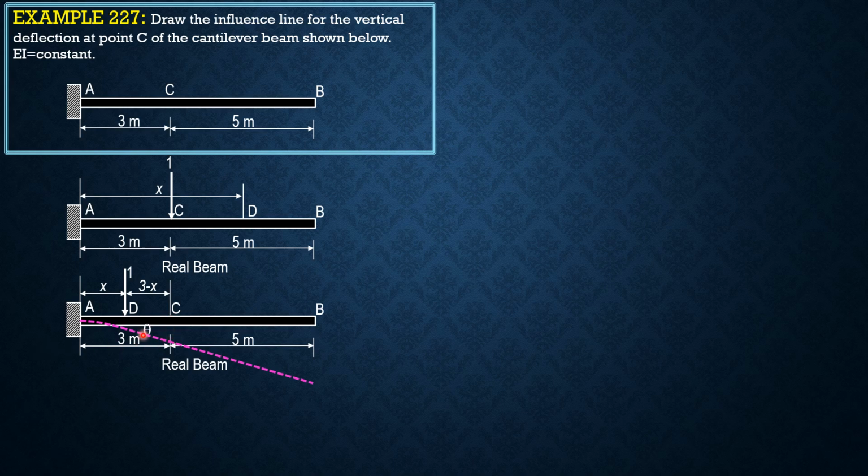so that the vertical deflection at C consists of moment at the wall, length squared, which is in this case x squared, over n plus 2, then plus this distance times theta, 3 minus x times theta. And theta is moment at the wall, length, which is x, divided by degree of the moment diagram by parts, plus 1.